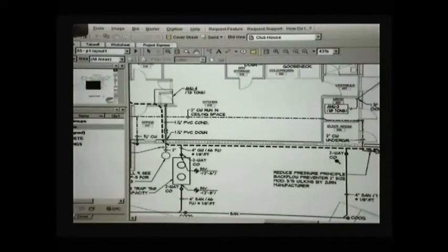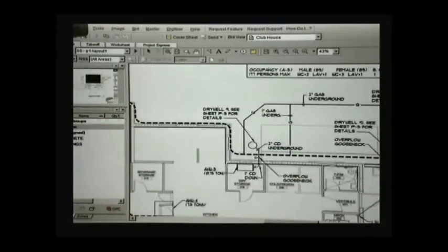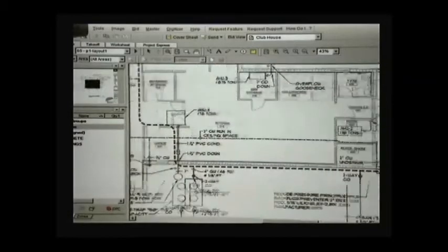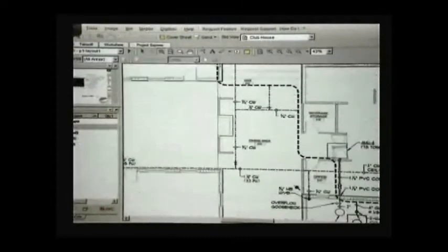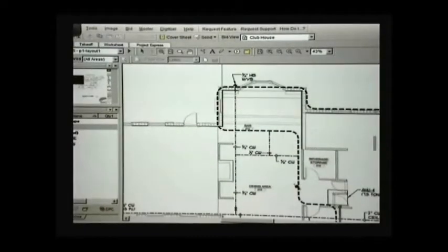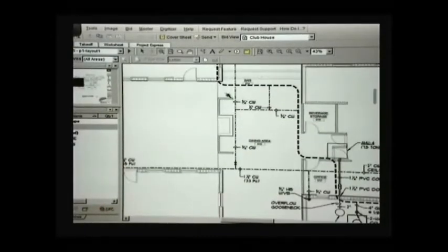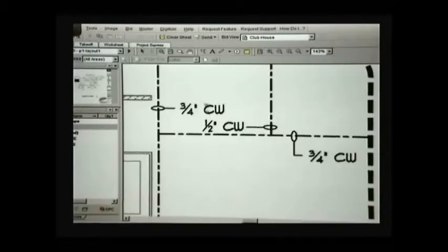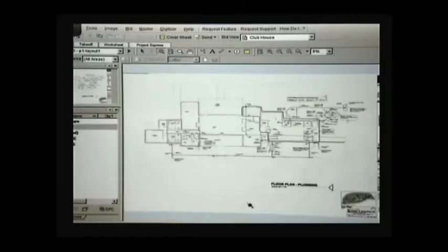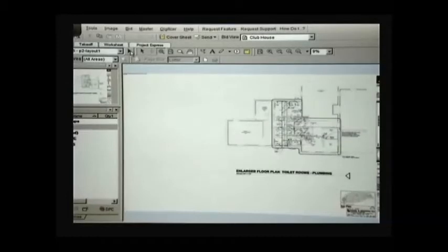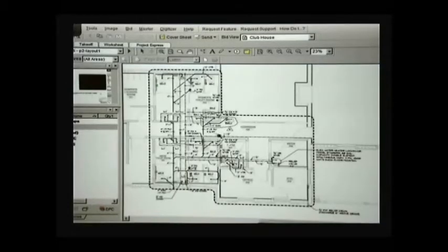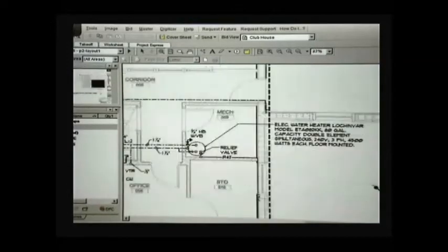Okay. Then, of course, you have the restrooms that have water that's coming from the sinks and from the water closets, and you need to collect that water. So they normally will tell you what is the diameter of the pipe. This is 3/4, 1/2, and you need to read the notes to be familiar with what material they're using, or what is the usage of that line.